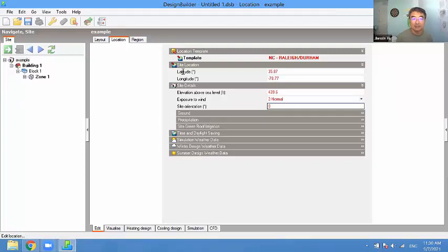That's the default direction for north arrow. If you'd like to rotate the north arrow, which means you're also essentially rotating the building, you can change this to 90 or 270. The north arrow will change. But for our exercise today, we're going to keep this at 0.